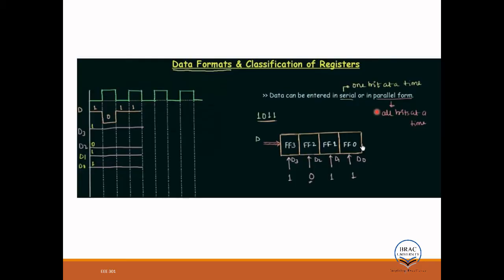Okay, so we already discussed this, but I want to emphasize this truth table. Say your override is low, so low means override is activated, right? So if override is activated, this is taking charge, so it doesn't matter what the clock is, right? It is getting the priority because this is an asynchronous action. So if it is getting the priority, then what will happen? Just consider all of the flip-flops' initial value was 0 0 0 0, right?